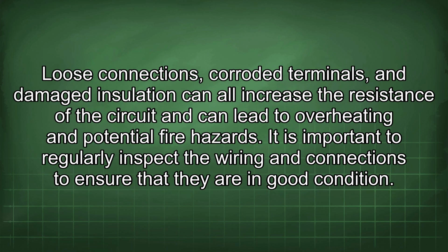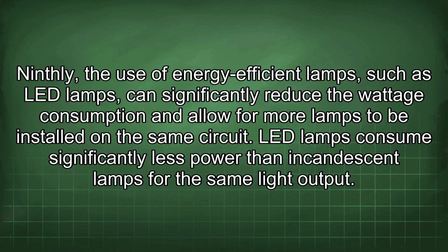Eighthly, the condition of the wiring and connections should also be checked. Loose connections, corroded terminals, and damaged insulation can all increase the resistance of the circuit and can lead to overheating and potential fire hazards. It is important to regularly inspect the wiring and connections to ensure that they are in good condition.